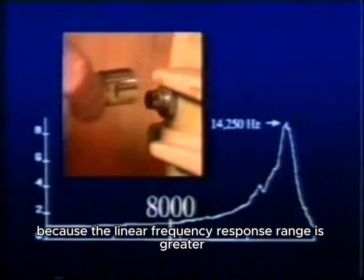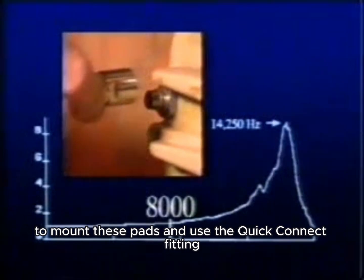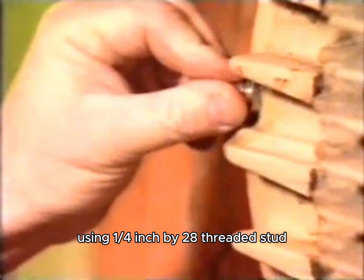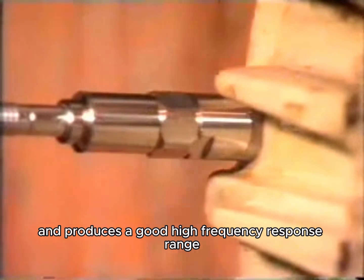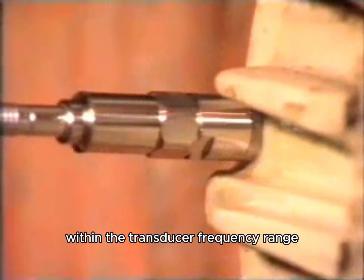Because the linear frequency response range is greater for quick connect mounting than magnetic mounting, there may be equipment that warrants the extra time to mount these pads and use the quick connect fitting. The pad can be stud mounted using a 1/4 inch by 28 threaded stud, or it can be glued in place. After the quick connect pads are installed, the data collection is simple and produces a good high-frequency response range suitable for capturing gear mesh and other high frequencies within the transducer frequency range.